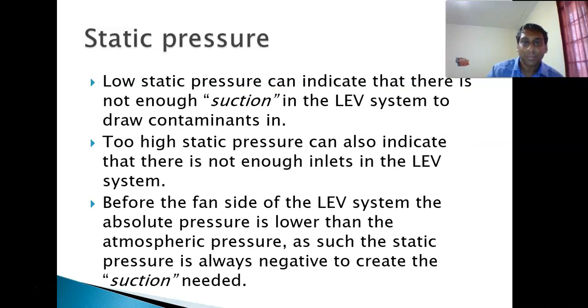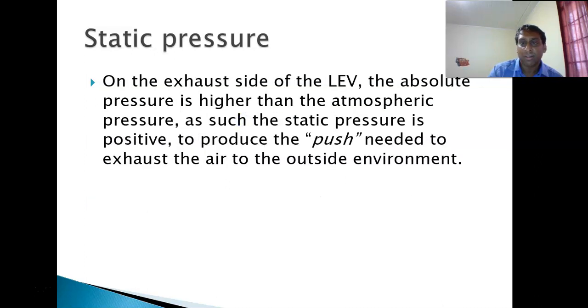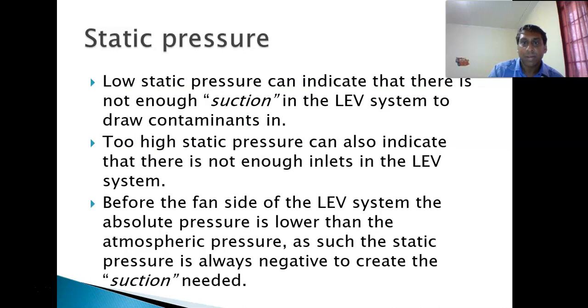Too high static pressure can also indicate that there are not enough inlets in the LEV system. Before the fan side of the LEV system, the absolute pressure is lower than the atmospheric pressure. As such, the static pressure is always negative to create the suction needed. I was saying this before when I thought that I had put something in the slide on it.